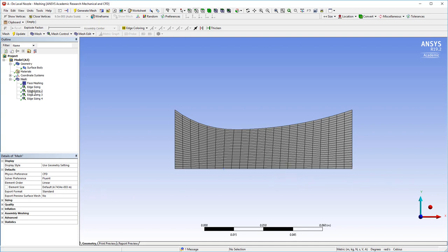And the benefit of doing something like this is that if we look at the statistics, we have 550 elements in this system, and we have saved a lot by having elongated elements in the axial direction. This may not be sufficient for the actual analysis, but I'm just showing you the means here. We may be forced to increase this number of elements substantially for the actual simulation later on.